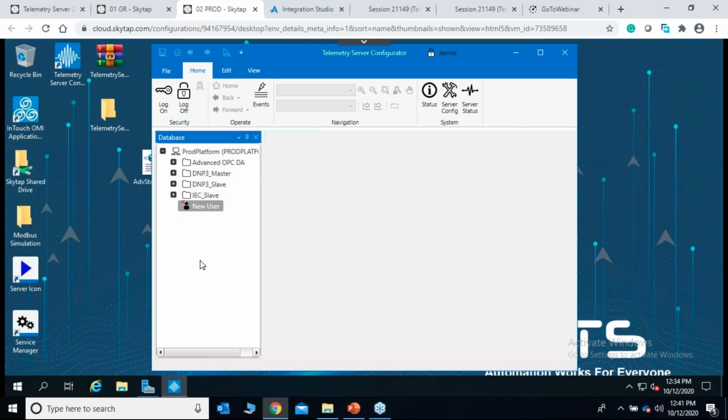Yes, sure. Sorry for that. For DNP3, will incoming socket connections be supported? Connection to be initiated by the field RTU, not the server? Yes, actually, it will support connections, and it shall be initiated by the RTU based on class configurations, if this is what he asked for.